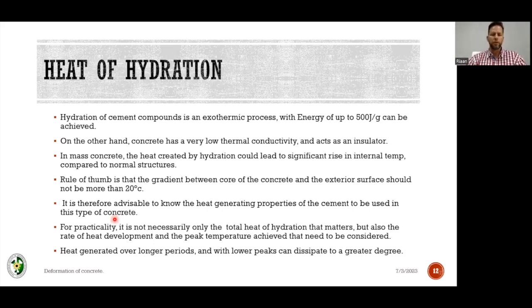removing the larger particles. Now, why would a large concrete test cube be a problem? Your MPa is a force over area. If you have a big block, you need to put one hell of a force on that. If you have a small block, you can apply less force, do the calibration and the calculation. You can calculate, okay, if I apply X kilonewtons to the hydraulic ram over my 100 by 100 test cube, I've got 30 MPa, 32 MPa, whatever I've got.